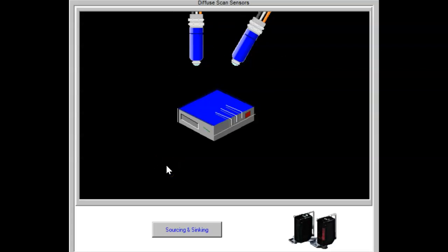Diffuse scanning uses light to detect the proximity of an object. Matte surfaces, non-shiny, such as wood, rubber, cork, dark plastics, etc., absorb most of the light directed at them. The light that is reflected is scattered equally in all directions. Because the light is scattered, a very small percentage of it actually reaches the photoreceiver. Therefore, scanning distances are limited to approximately 6 inches. Alignment is not a critical factor with diffuse scanning. This type of control is also available using fiber optics.